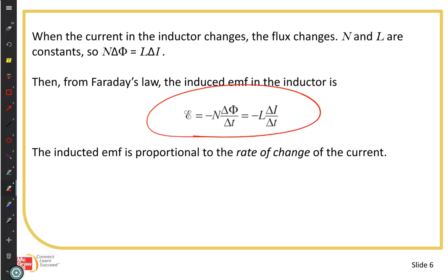And so the current creates a magnetic field, and because we have a changing magnetic flux, it induces an electromotive force that's opposing the change. So if the current is increasing, then I'm going to have a voltage that's going to try to oppose that current. The voltage ends up going from positive to negative. It's losing energy. The energy is going into creating a magnetic field.